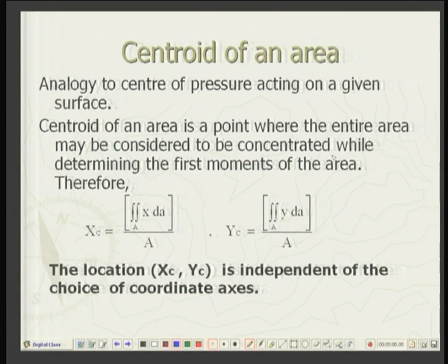Suppose there is a given area and some fluid pressure is acting on it, and it is acting in a normal direction to the area. Then you remember we replace that distributed force system with an equivalent force, a single concentrated force acting through a point which we call center of pressure.